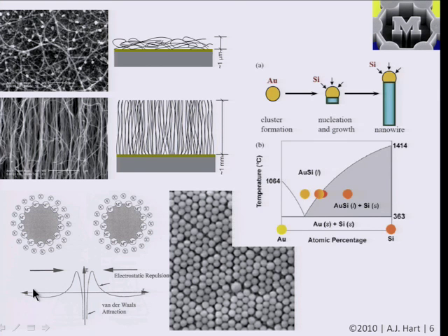And then, for example, what I alluded to about surface energy and melting is important in many areas, but one area it's important is in synthesis of nanotubes and nanowires. For example, the fact that small particles of metal melt at temperatures beneath the bulk melting point governs the synthesis process. For example, why gold nanowires can be grown at temperatures below the bulk melting temperature of gold.